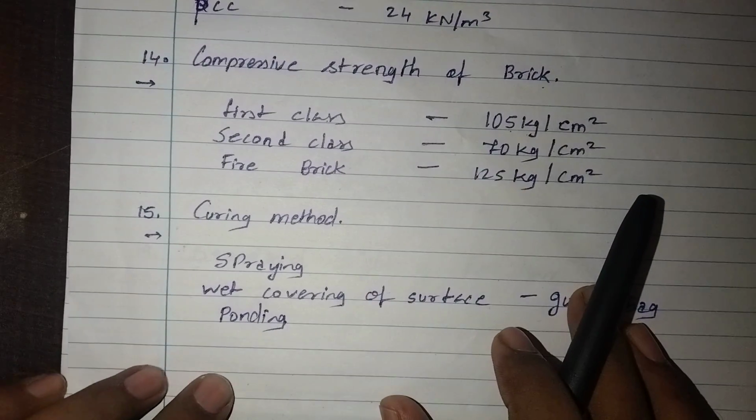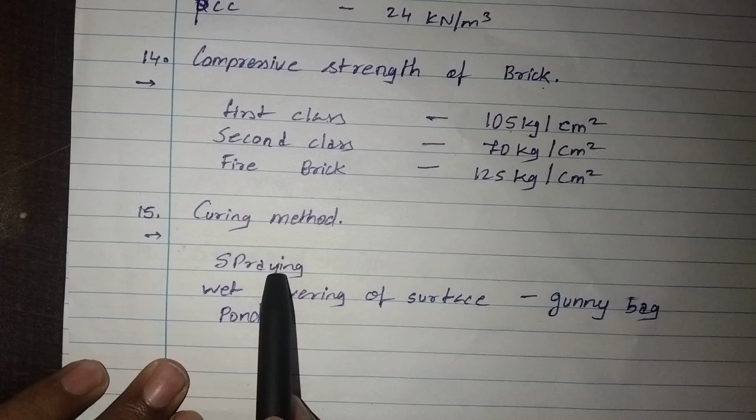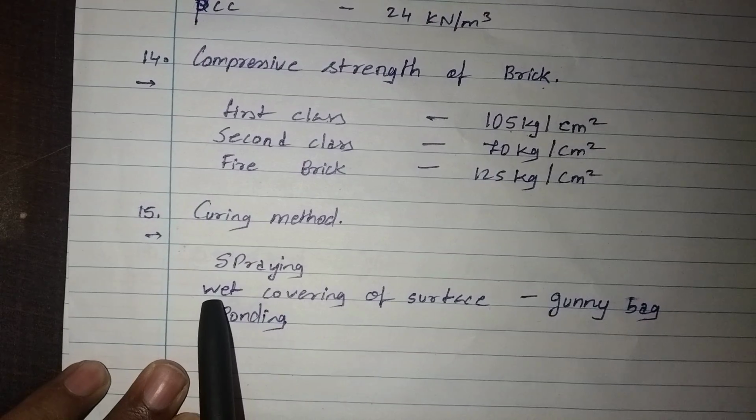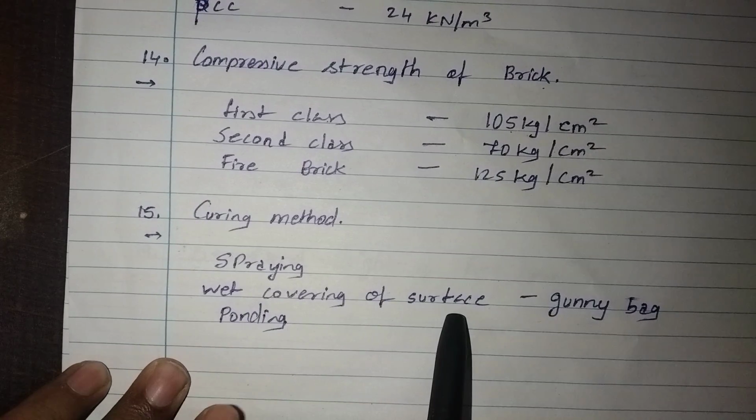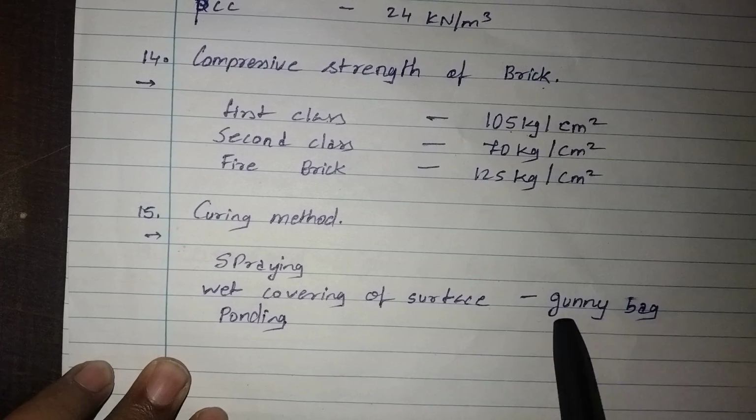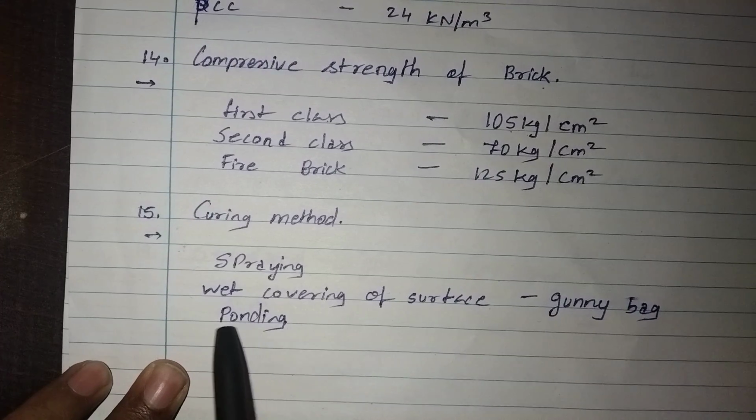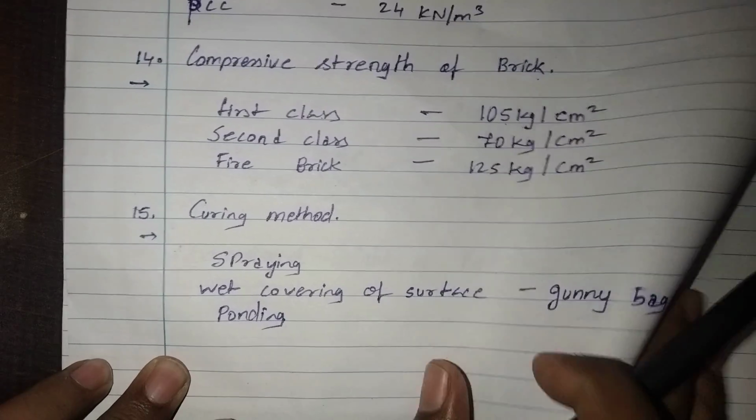Curing method. Okay, there are three ways. Spraying method, next the wet covering on the surface by gunny bags, and water ponding, which is mainly done for the slab. Okay,